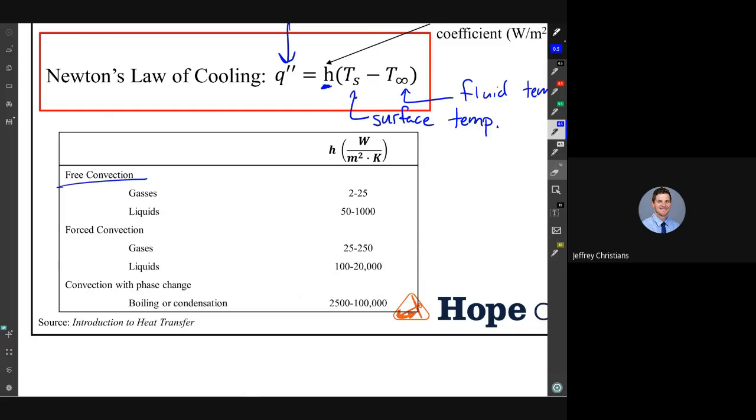They're called schlieren, which is a fun German word, so you can impress your friends at the next cookout. The lines you see are actually from the change in density of the air. It's essentially the hot air rising off your hot grill. So that would be free convection. You don't have a fan blowing.